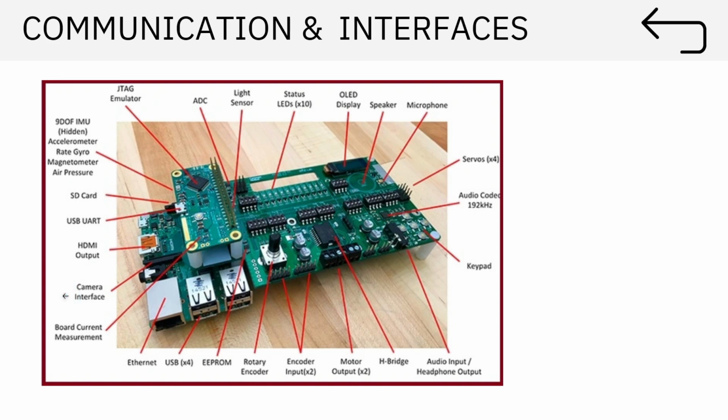So in terms of communication interface, in our requirement we have dual CAN. That means one of the DB9 connectors we can use for dual CAN. The other can be used for powering it up, and there can be some interfaces that we can expose. To program the board, we can have a JTAG connector.